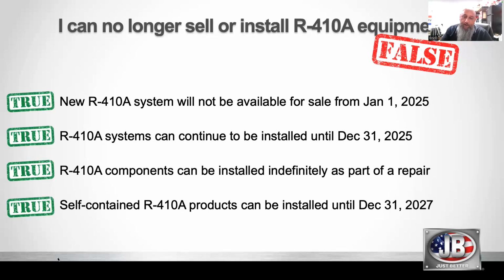Yeah, no, you're right. So guys, if they've got it in their inventory, they're okay to sell it for a further 12 months. But the thing I would say is don't count on that, because most of the manufacturers are either switching over or soon to switch over to the new A2Ls. So the 410A equipment is going to dry up, I think, pretty quickly. So I don't think we're going to have a huge inventory surplus of it.